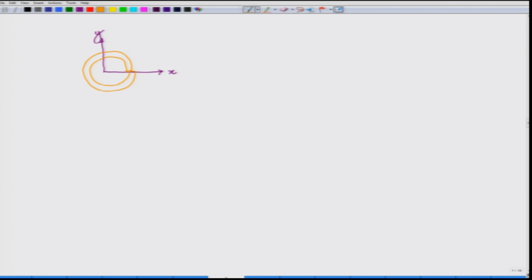So, you see that this is a tube, we are looking through the center axis and we are only looking at the cross section. You can see that where there was a cut in this Volterra hollow tube, along that cut there is a displacement along the x direction, and this displacement, from what we know about dislocation, can be termed as the Burgers vector B. So, this is one kind of translation.